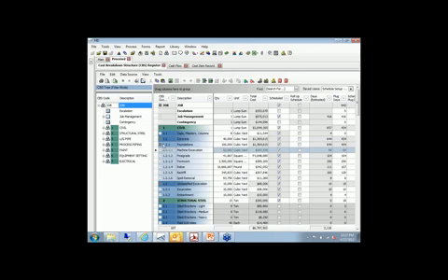Okay, probably the more common scenario that we see is folks using hard dollar to create the estimate initially, perhaps doing the quantity takeoff, working through at least a preliminary estimate to the point where we've got some costs, as you can see here, and then using that to go the other direction. Let's use that to create the initial schedule in Primavera using the same structure, and then perhaps refining that structure once we get into Primavera. So this whole structure from the hard dollar side can go into Primavera and create the schedule.